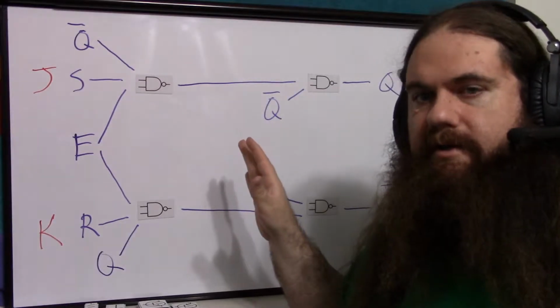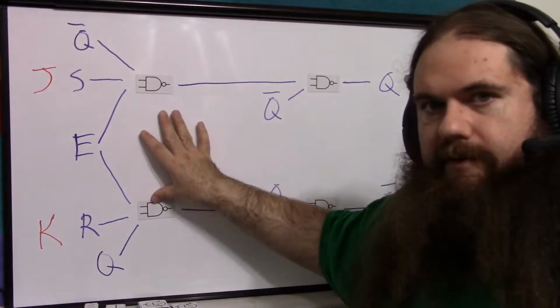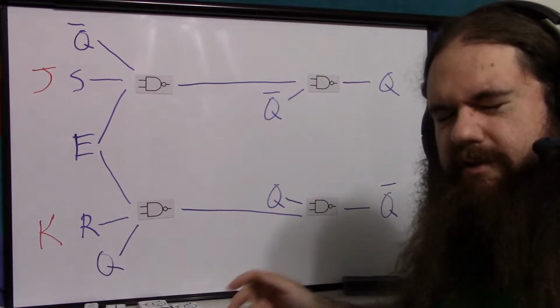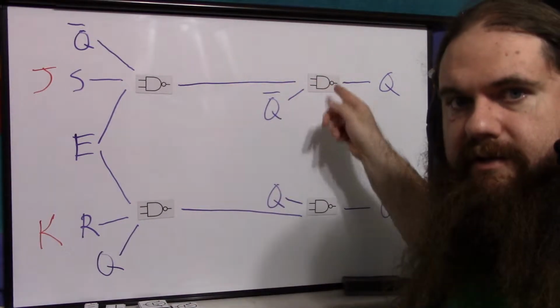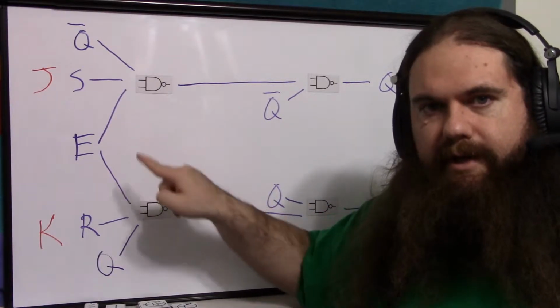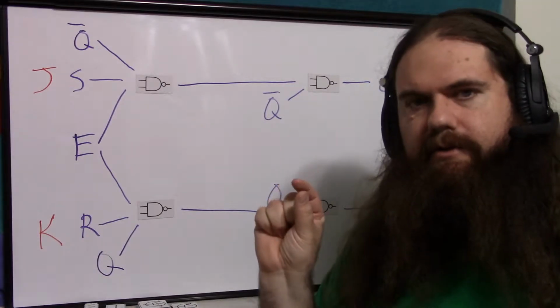It's the same thing as an SR flip-flop. And so each of these is 3 inputs, so that's 3 transistors each. These are 2 inputs, so that's 2 transistors. So it's 3, 6, 7, 8, 9, 10. 10 transistors. And then you can do just like before and have your enable signal shared, have a single transistor.